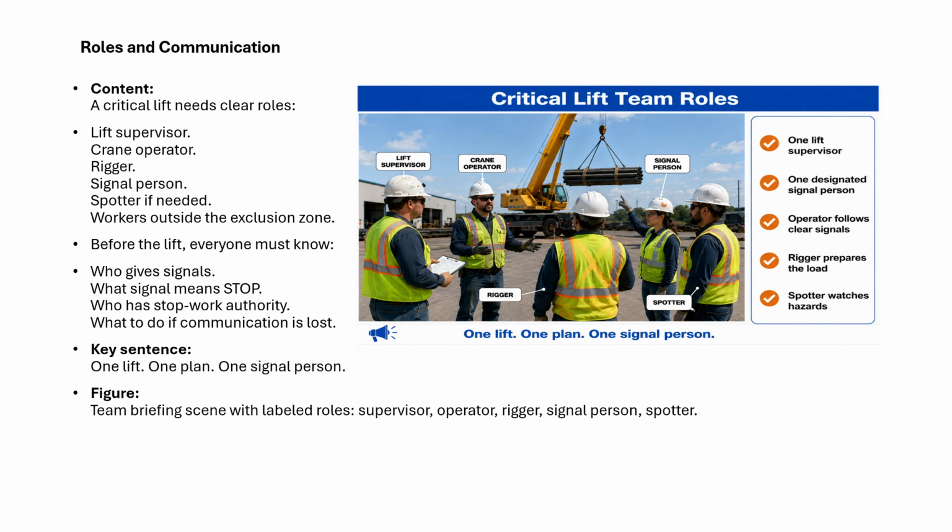Before the lift, everyone must know who gives the signals, what signal means stop, who has stop work authority, and what to do if communication is lost. Key sentence: one lift, one plan, one signal person.